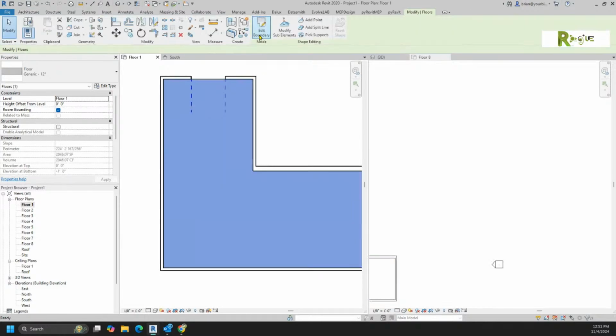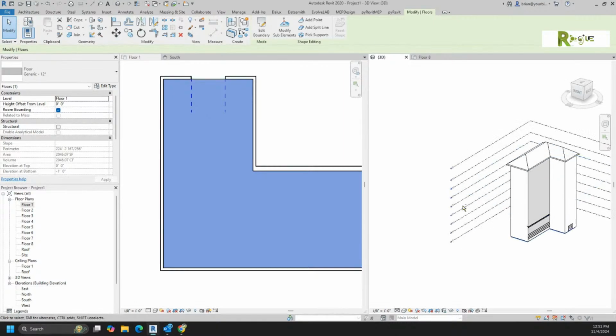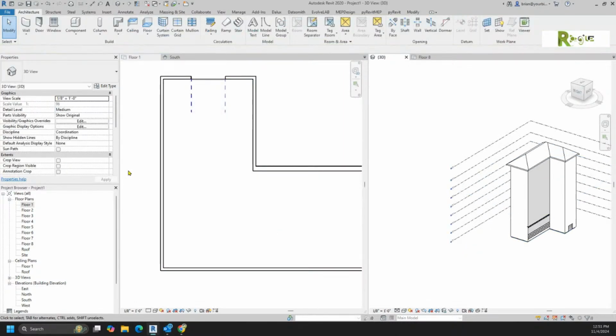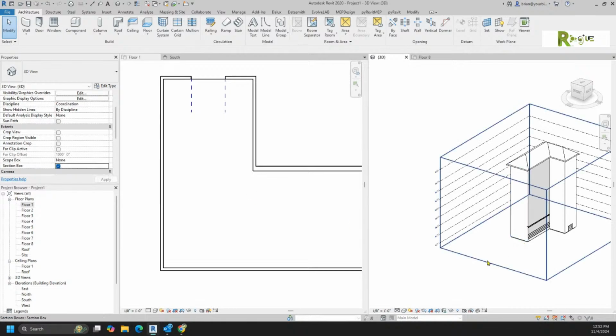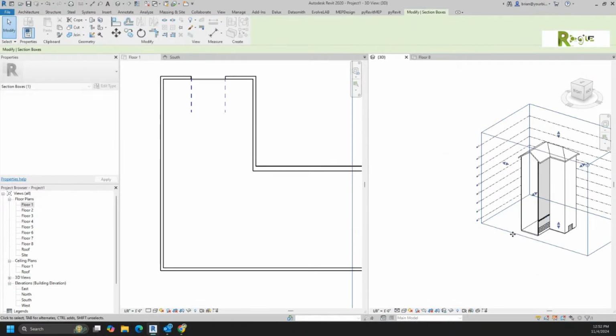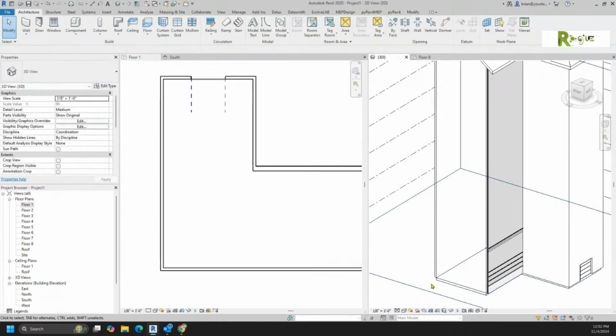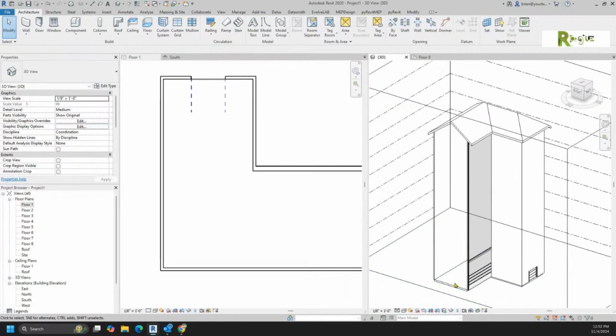So now that then puts us a floor, right, 3D. Now, there's a really neat command that allows me to come in here and turn a section box on. And then I could take this section box and I could pull this guy back here like this. And you see how I have this last floor, the first floor? Yeah. Well, I could take that first floor.